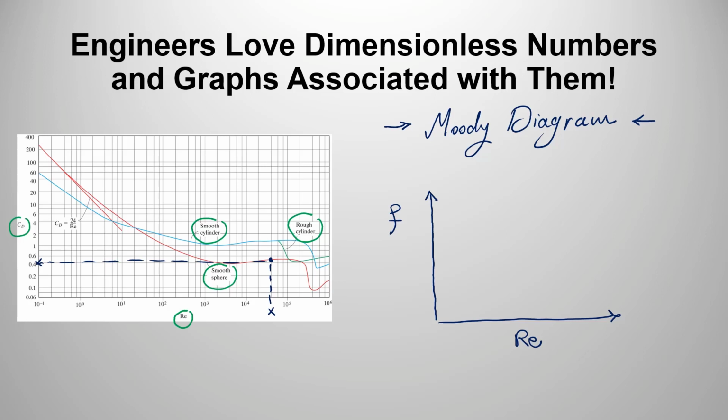Now, you still remember that Reynolds was developed for two different flow regimes. One regime was laminar, and the other one was turbulent. For laminar flow, you had a line representing the variation. Let me sketch a better line. You had a line telling you about the variations of Reynolds and f. And if you remember, the equation for this line was 64 divided by Reynolds number. Now, for the turbulent regime, for a smooth pipe, for example, it was something like this. For smooth pipe.